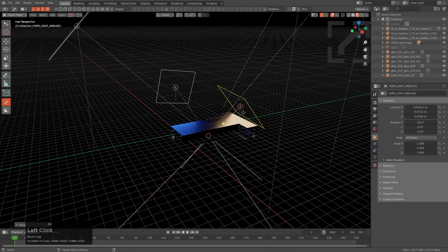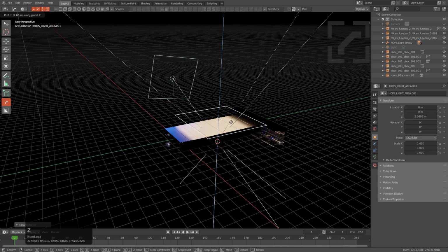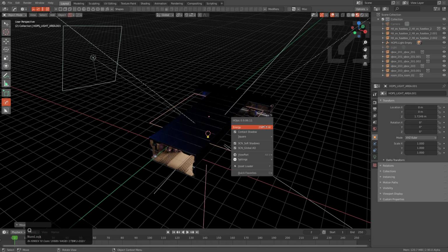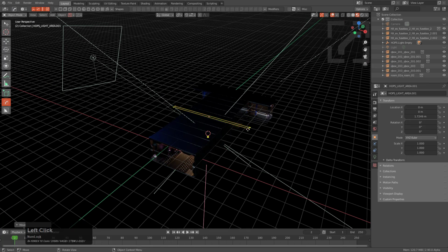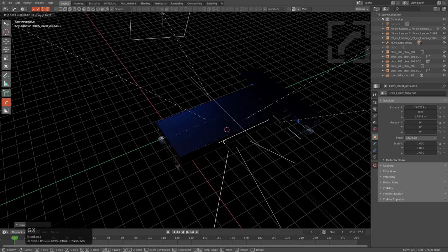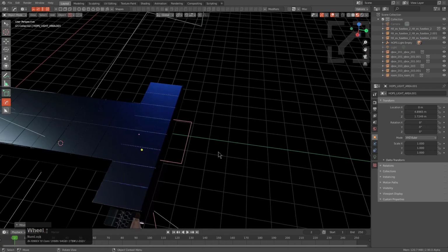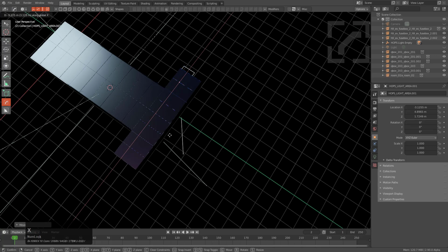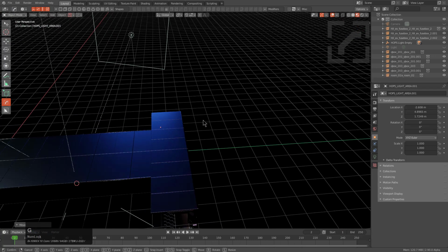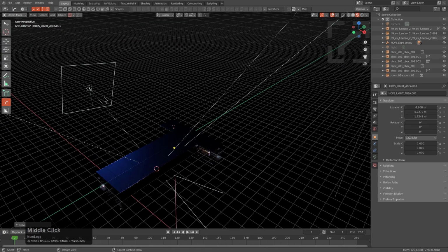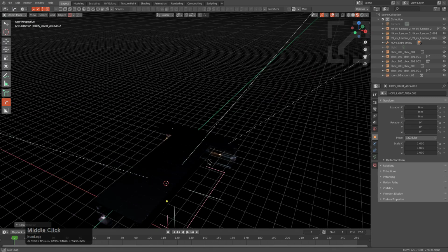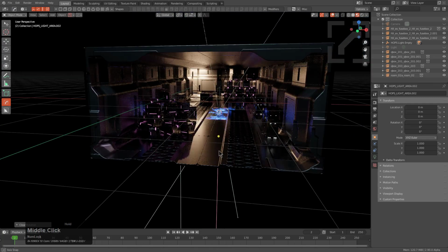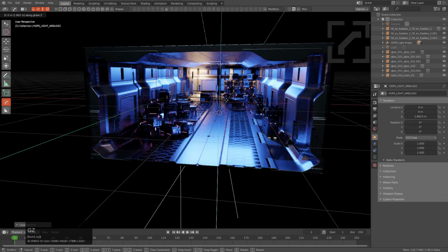but for me, I won't be needing it because my goal is to place it, press Alt G, Alt R, raise it up, maybe even press Q and change it from square to rectangle, and just grab the controls and just move these lights around just to play with different locations. It doesn't even matter what light locations are right now as far as their absolutes, because the goal isn't to set this up as the final configuration, but to just give it a starting point for whenever I do a rescroll of the light rig.